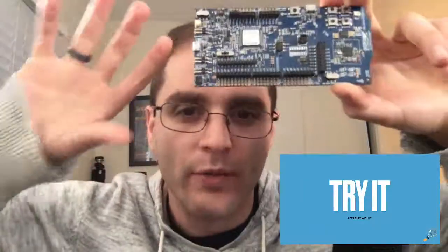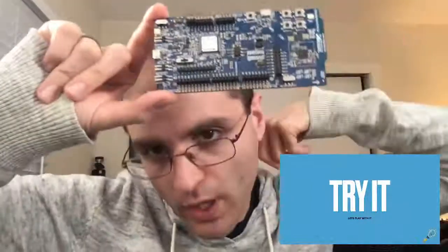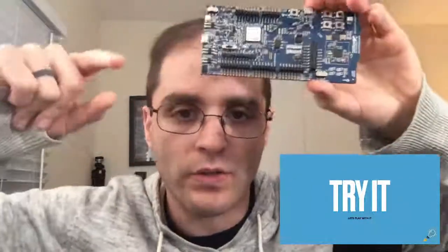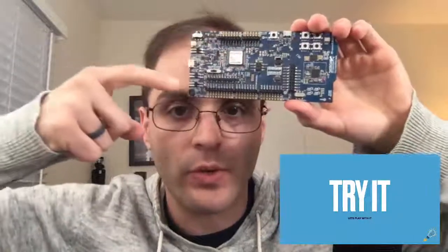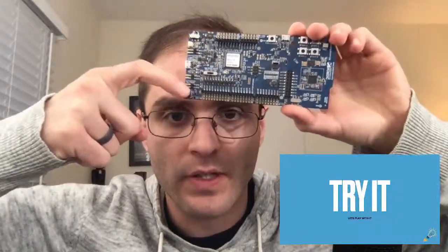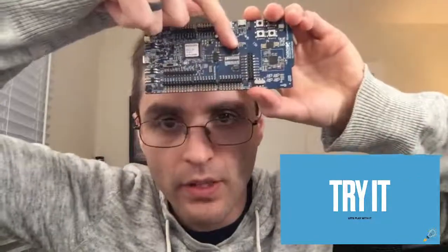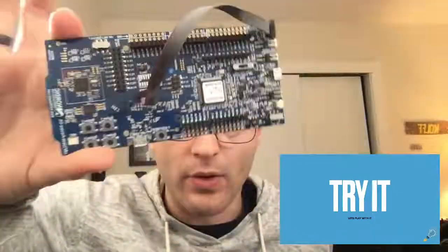If you ever want to keep this defaulted to using external, and then also want to program the onboard one, you could always jump from here. So this is the output, and I believe this is the input. So you can actually take your cable here and jump it between the two once you've made that modification, so that now this is set up to program the onboard no matter what.